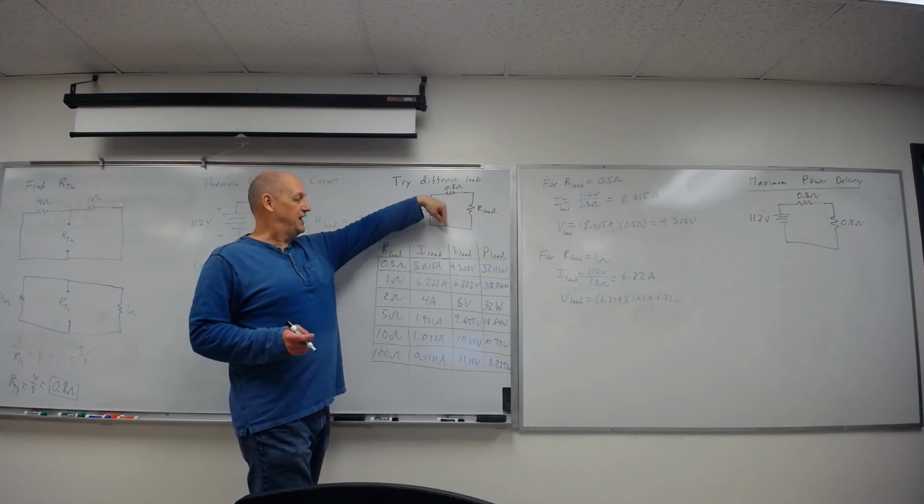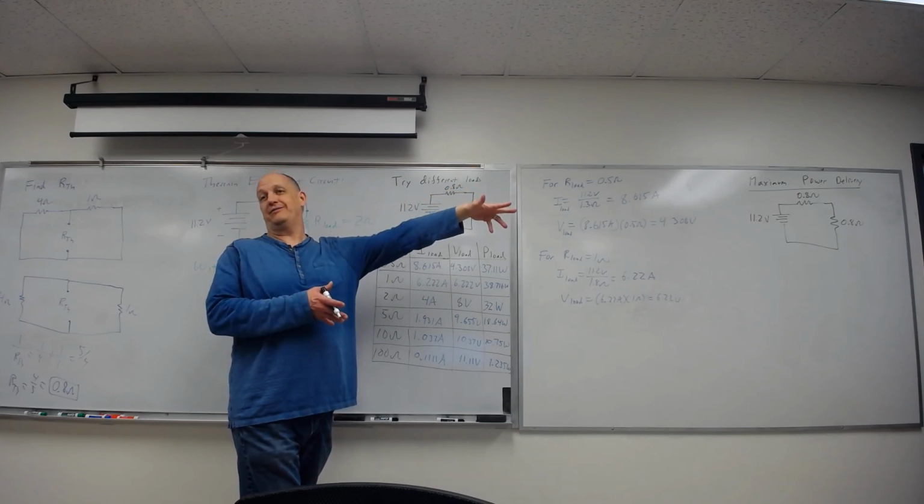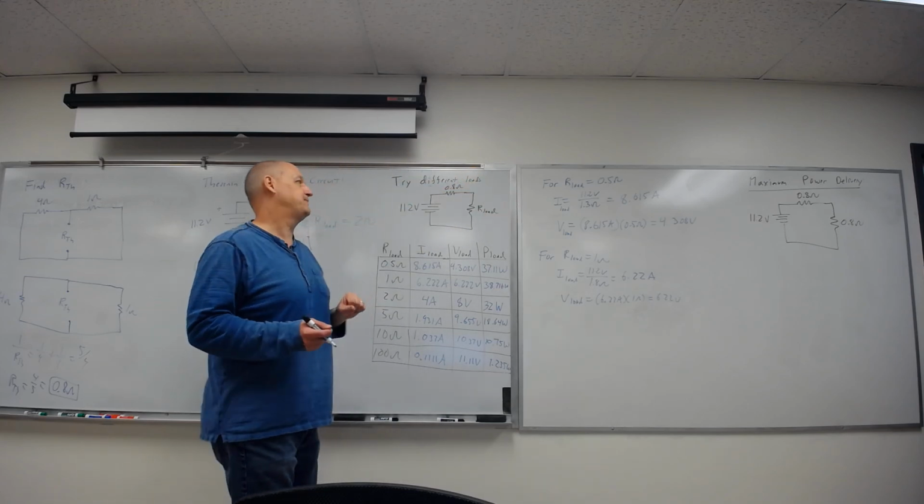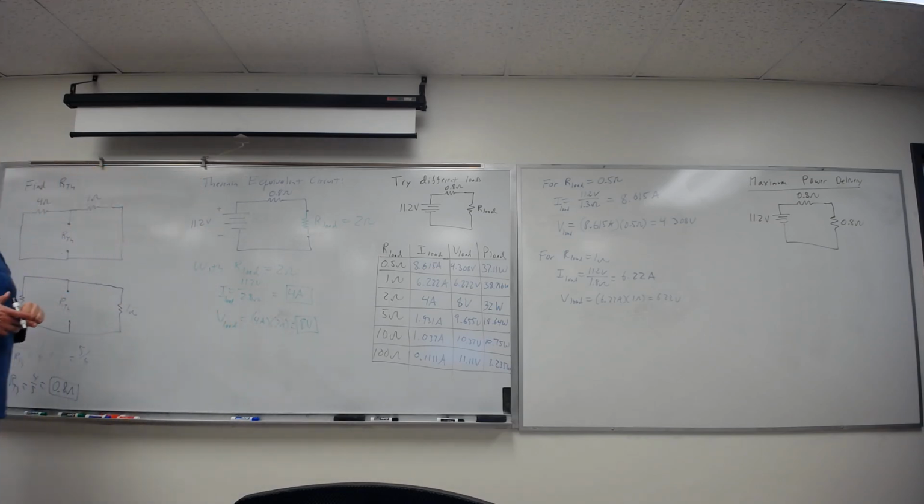And a lot of times I'm really not about maximum current or voltage, I'm about maximum power delivery. I'll take the power created by my source and deliver it. This has some interesting side effects. My actual cables, which we'll be talking about next week, and how much power they take out. If I want absolute maximum power delivery, I need my load to be the same resistance as the resistive loss I have on the cables that deliver voltage and current. When you think of them as being zero, it might be tempting to think, well, I do want my resistor small because it maximizes my current. Makes my power highest.